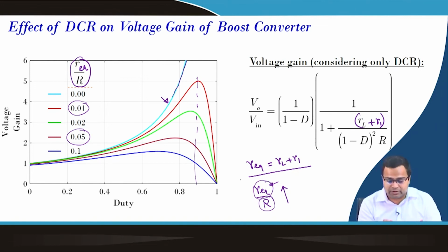So, in a boost converter, the practical voltage gain is limited by this parasitic drop, which is primarily due to the drop of the on state resistance for a synchronous boost converter. For an ordinary, conventional boost converter, it will also be a function of the diode drop.